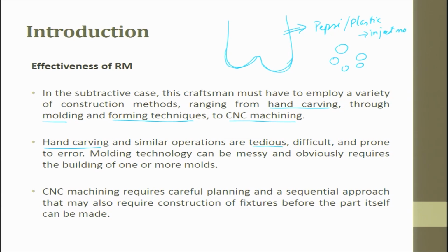It will be made out of injection molding. So, if you see the bottom part of those shoes, wherever it is there inside, this has to be first machined, and many a time, since it is very difficult for us to machine, we use the EDM process for making a die. The die is used in injection molding. So, here we spend a lot of time after doing EDM, we spend a lot of time in finishing.